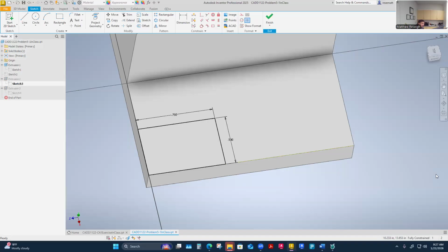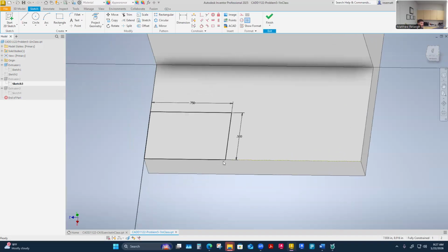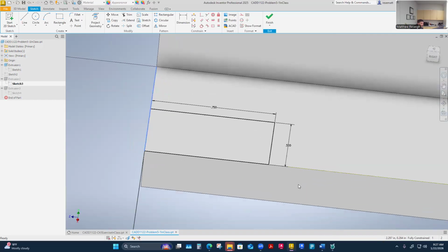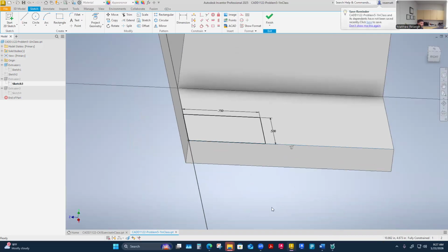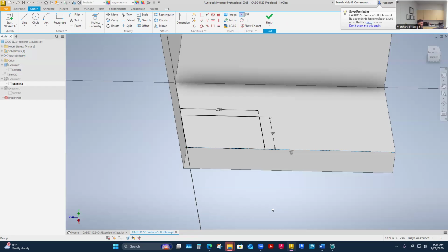And usually I will delete that pink geometry because it's no good to me anymore. And I usually can't reconstrain the pink geometry. So I usually have to identify what moved that's pink if I needed it. Then I need to reestablish it maybe and redimension to it or something. And so I don't have any pink geometry here. Mine actually stayed constrained. So everything I've changed so far in my solid, these edges are still kind of the same edges they ever were that I was dimensioned off of. So that's why that didn't blow up.